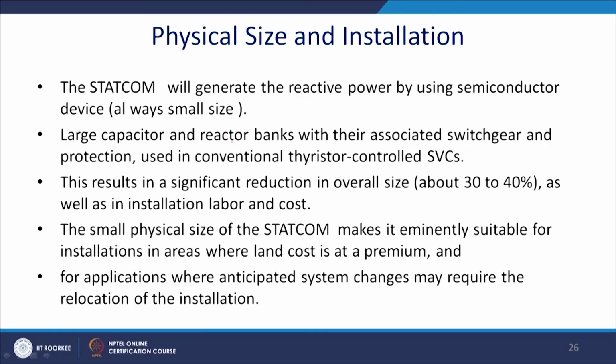And what about the physical installation? The STATCOM generates reactive power by using semiconductors and thus has a small size. Large capacitors and large reactors, with the associated switchgear and protections and all those things, are used in thyristor-controlled SVCs, so the system is bulky. As a result, a significant reduction of the overall size, about 30 to 40%, is possible in the case of the STATCOM. The small physical size of the STATCOM makes it eminently suitable for installation in areas where land cost is at a premium. That is also an important thing.